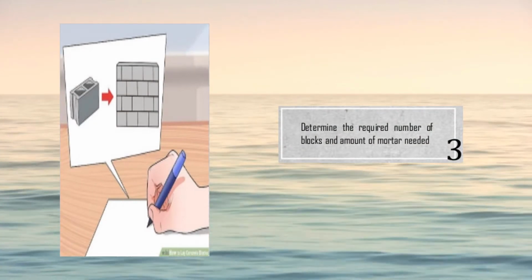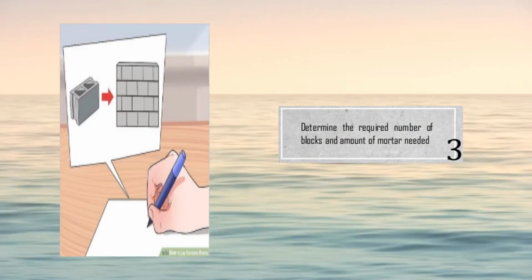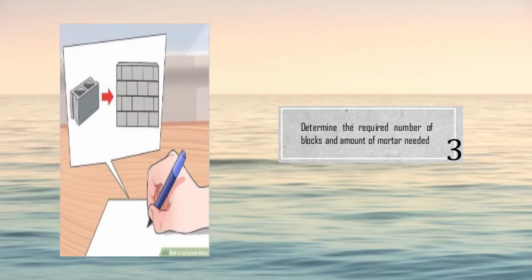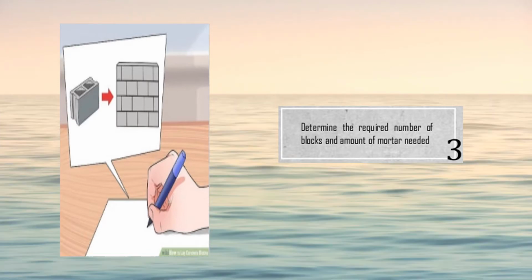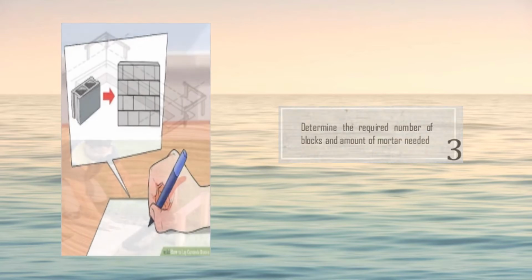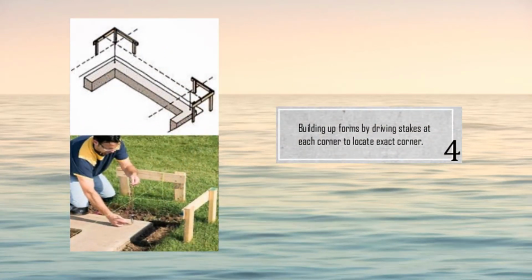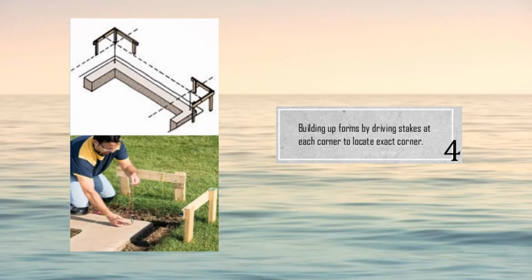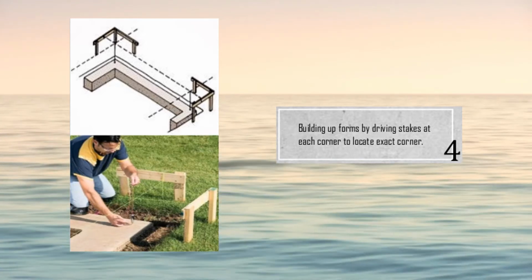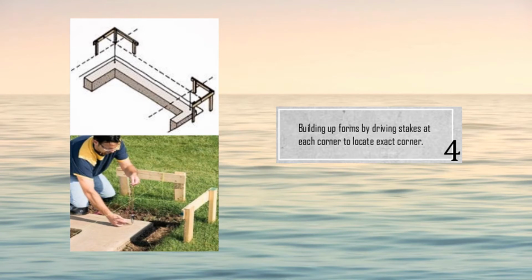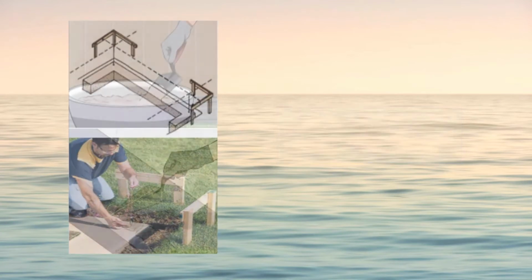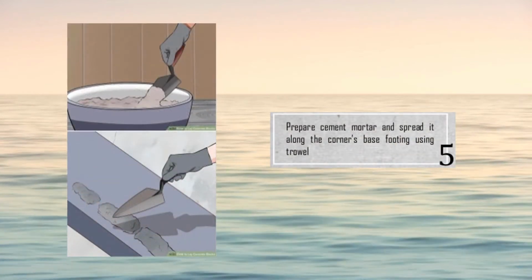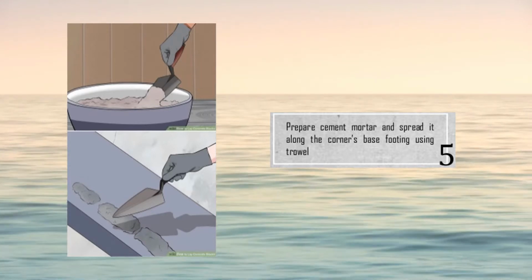Third, calculate to estimate the quantity required for block and mortar. Fourth, prepare setting out for block position. Fifth, mixing and ratio of mortar to join the block.